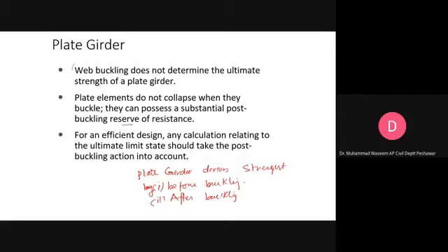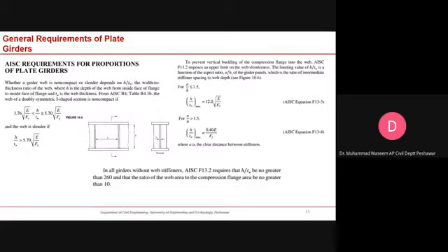So you will see that in case of shear, there are two types: before bending of the flanges and after bending of the flanges, it has strength. It doesn't mean that if the flanges or the webs are bent, it will have no strength, and this is a serious limit state. So before the buckling and even after the buckling, it has some strength left. You have to take that into account.